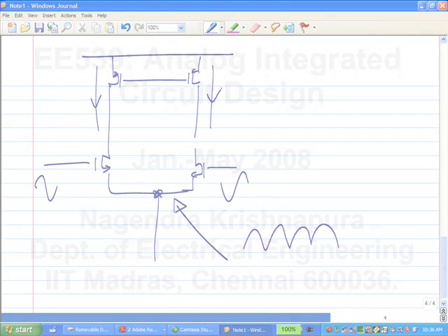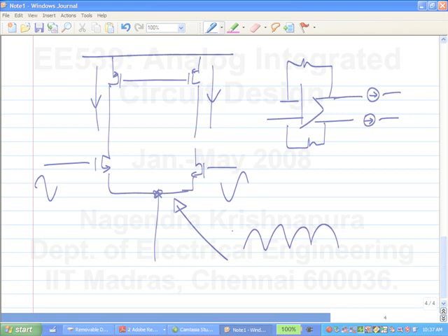So it entirely depends on what disturbances you expect. And sometimes it may be some startup, or let's say some common mode current is being drawn and then suddenly it becomes zero. How fast does it come back to the common mode voltage? Or if you have a common mode step, how fast does it get restored? That decides the bandwidth. Now why can this happen? It may not be a current source, it can be a capacitor also, right?